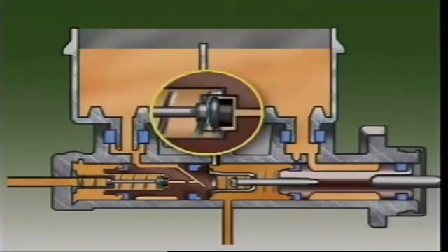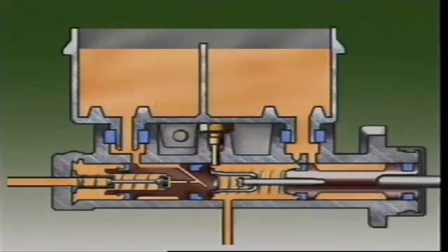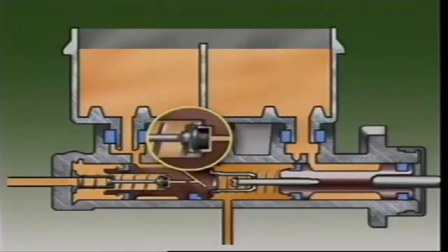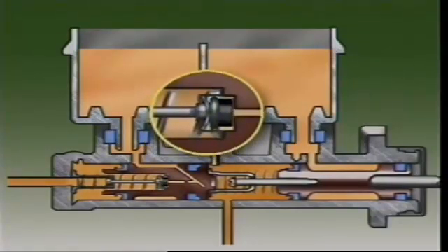At rest, the supply port is open and connects the reservoir with the front brake circuits. The primary piston still has an inlet port and a compensating port. When the brake is applied, the primary piston moves, which closes its compensating port. Fluid pressure in the primary circuit rises. It acts with the primary piston spring to move the secondary piston forward, closing the center valve.